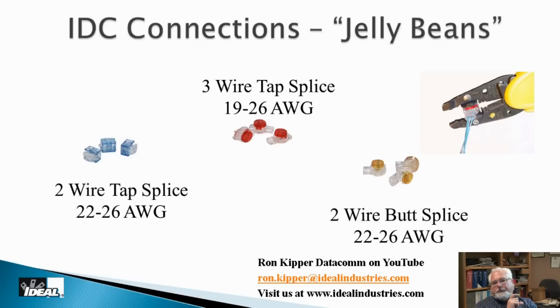And I occasionally see security guys utilizing these things, and they pull a lot of 18, but in a lot of cases, our phone wire is 24 gauge usually. So these things are for tapping and splicing phone circuits. And if you could imagine along the length of a telephone pair in a building, anywhere along that length, for old phone circuits, basically I can tap into that line and feed a phone. But I have to cut into the tip and the ring and go feed an extra phone.